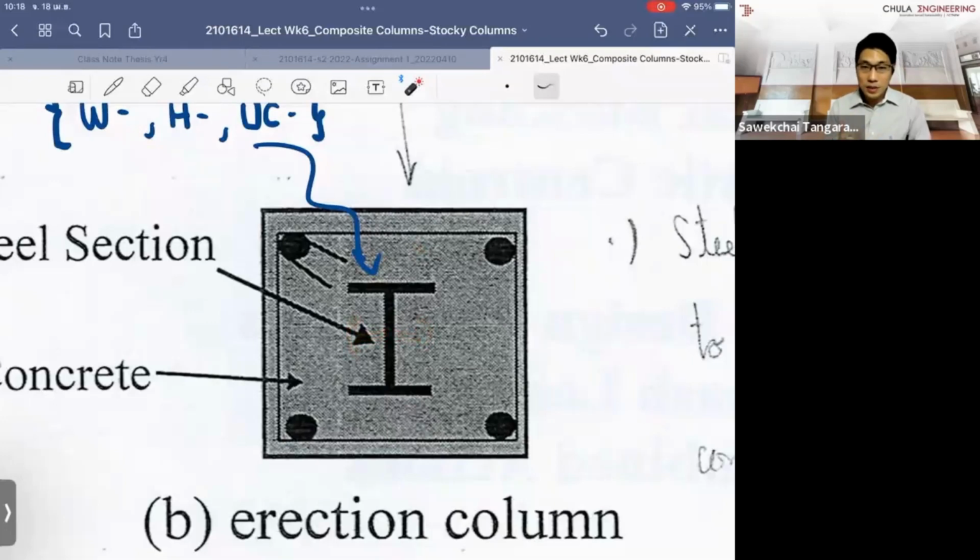So the purpose of the shear stud is to provide friction, because the two types of material come with different properties, starting from the elastic Young's modulus, which is different. The Poisson ratio is different as well. These different material properties can make slip, or some interaction of the two materials, and that will impact the capacity of the whole column that we are looking at. And this has been put into all the research areas.